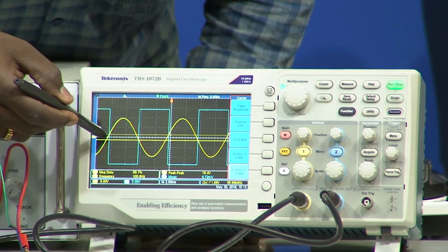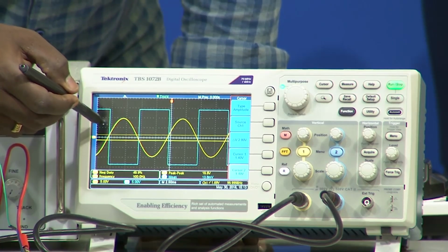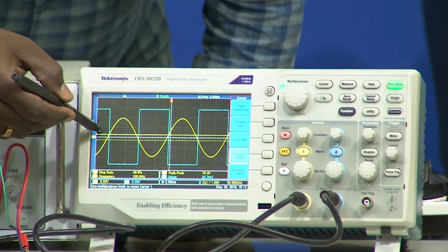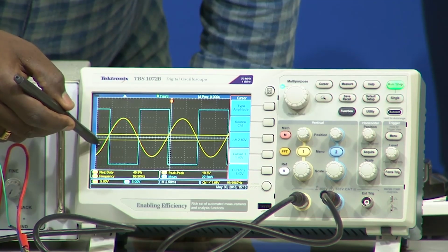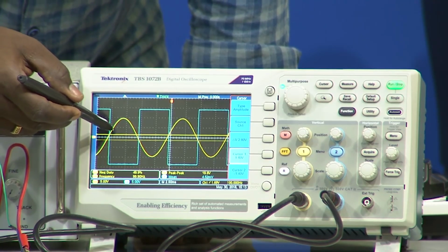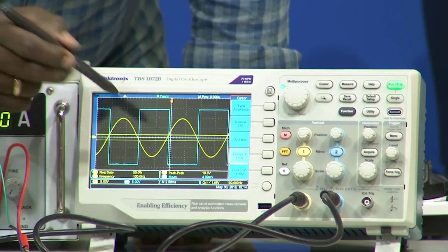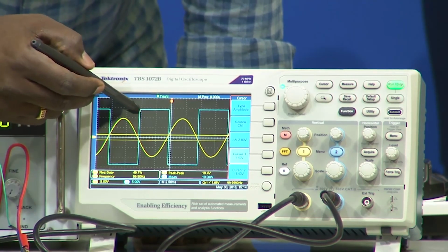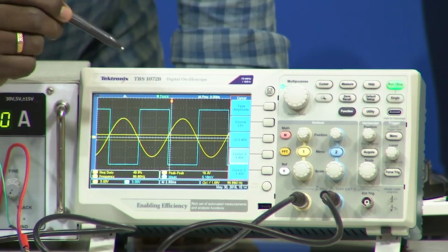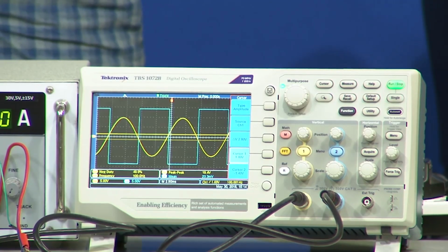When we look into this particular portion, this is one threshold and the bottom one is the other threshold value. I will go to channel 1, the dark yellow one: the first yellow line is the first threshold, the bottom yellow line is the other threshold. Now, when the input sinusoidal wave is greater than this threshold, the output is going to minus VCC, right. It goes to plus VCC only when the input is lower than the lower threshold value, right. So, it is clear that it follows our theory as well as our simulation.